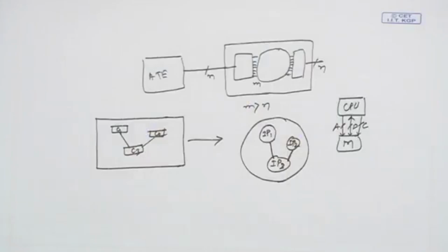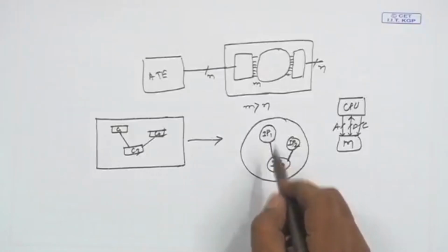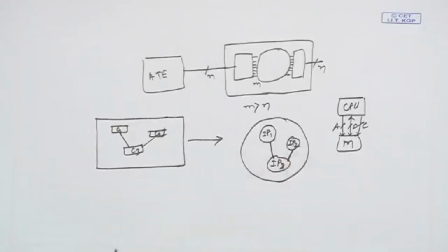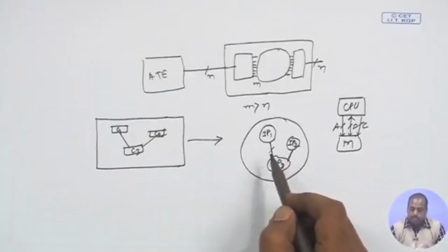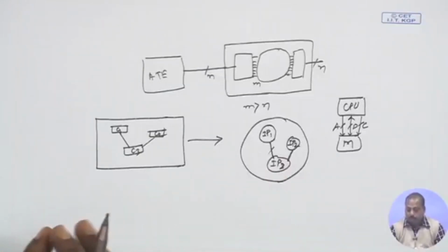As a result, a large number of lines need to run parallelly between the CPU and memory. So, this line that I have drawn from IP1 to IP2, if IP1 is CPU and IP2 is a memory, its width is significant. It is the sum of the widths of the address, data and control lines. So, that way we need a large number of lines.